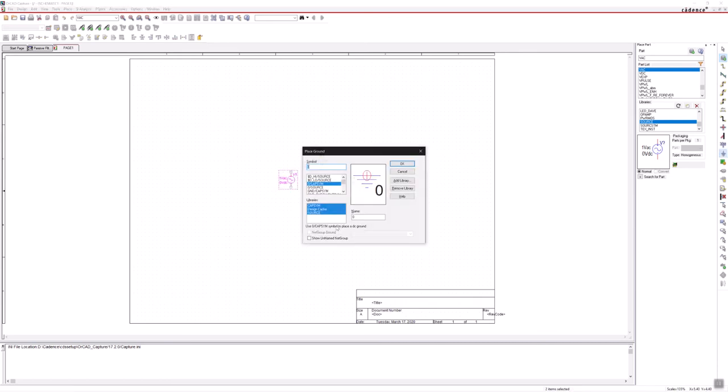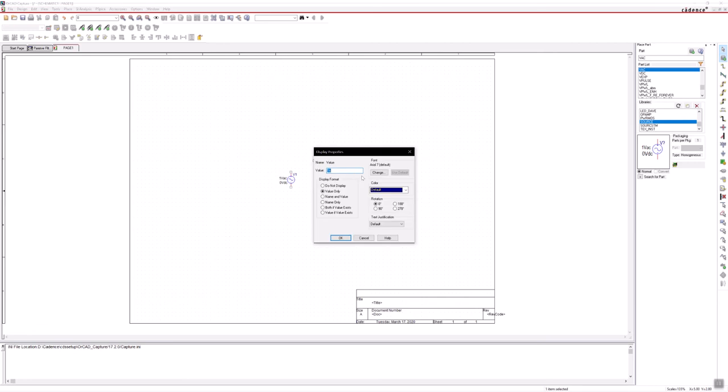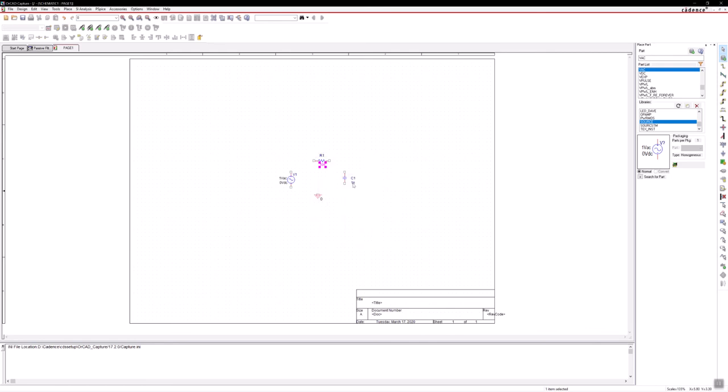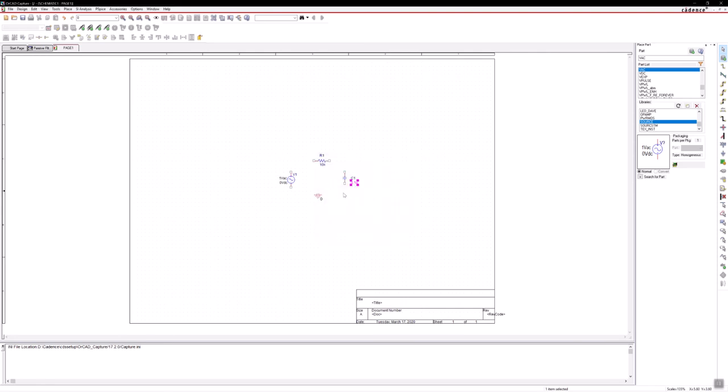Before I make any connections, of course, I have to put a ground in. So I put G for ground, and then I'll just place my ground. Then let's go ahead and change these parameters here. Honestly, I'm not even doing a design per se. I'm just picking some random ones to show you how you could do this. So let's have this be 10K, and we'll have this one be 0.1 microfarads. We'll see what happens. I just picked random values. I haven't even computed anything at all for this. And then, of course, we need to wire this up correctly.